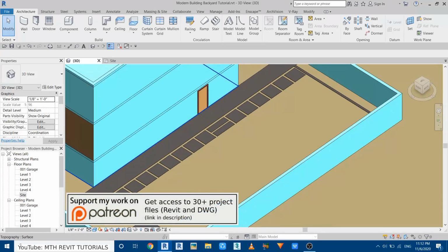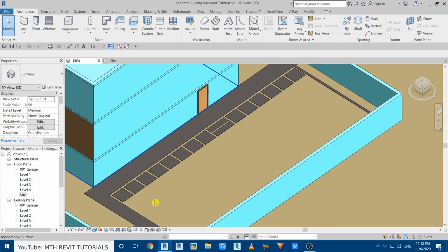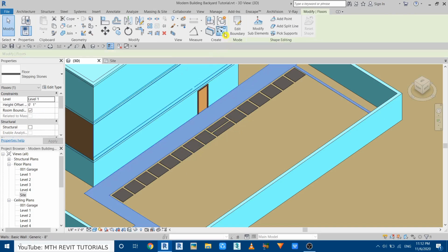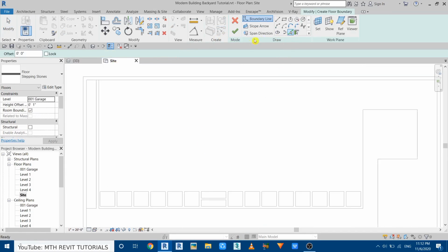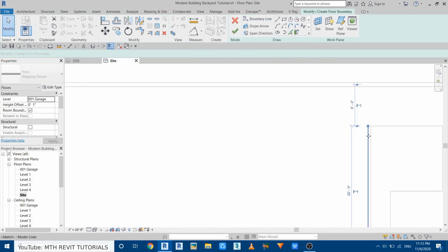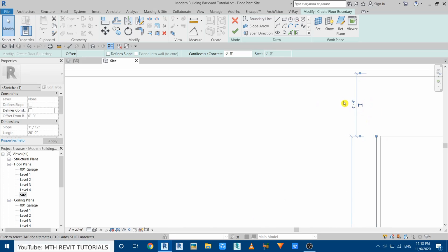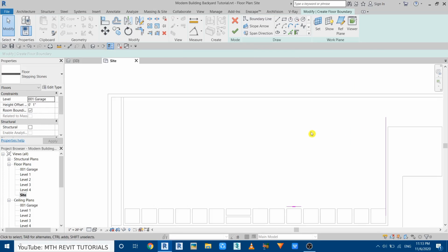So first I will create the border around the swimming pool, and then we will create the swimming pool. To create the border, I'm going to use the same floor. So let's select that, create similar, go to site plan, use pick lines, and let's give a 5 inches offset on this side here as well. And then we can just extend this on this side. It's 6 feet 4 right now, so I want to make it 4 feet 4, so we got 2 feet offset here. Perfect.